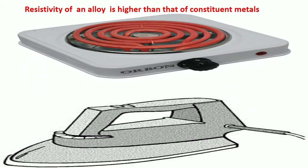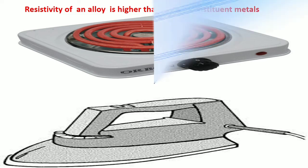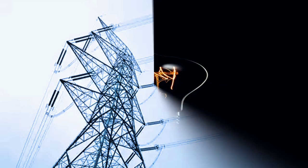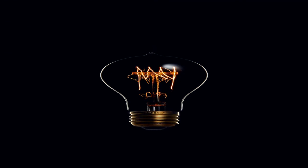The resistivity of an alloy is generally higher than that of its constituent metals. They do not oxidize readily at high temperatures. Hence, they are commonly used in electrical heating devices like electric iron, induction coil, toasters, etc. Metals having low resistivity are good conductors, hence copper and aluminium are used for electrical transmission lines, while tungsten is exclusively used for the filament of electric bulbs.